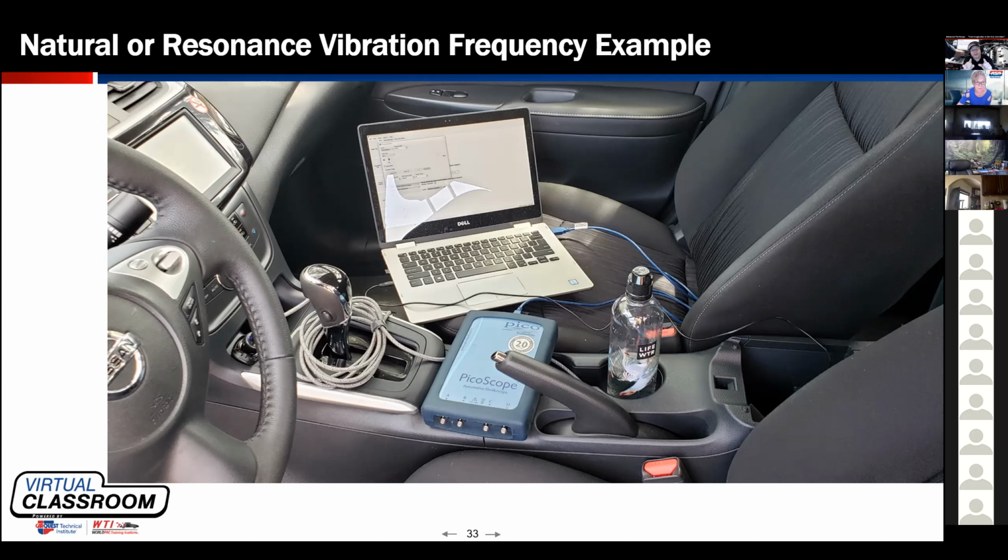And if you took nothing else out of this class, why wouldn't you at least look at a very, very inexpensive noise vibration app to start playing with, even if all you do is read all the information that's in it? It's wicked cool. Why wouldn't you at least get a free app for a frequency generator, plug it into a stereo system in a car, and prove what I'm telling you, that you can find rattles like you would find vibrations in the car? Just pretty dang neat, man.